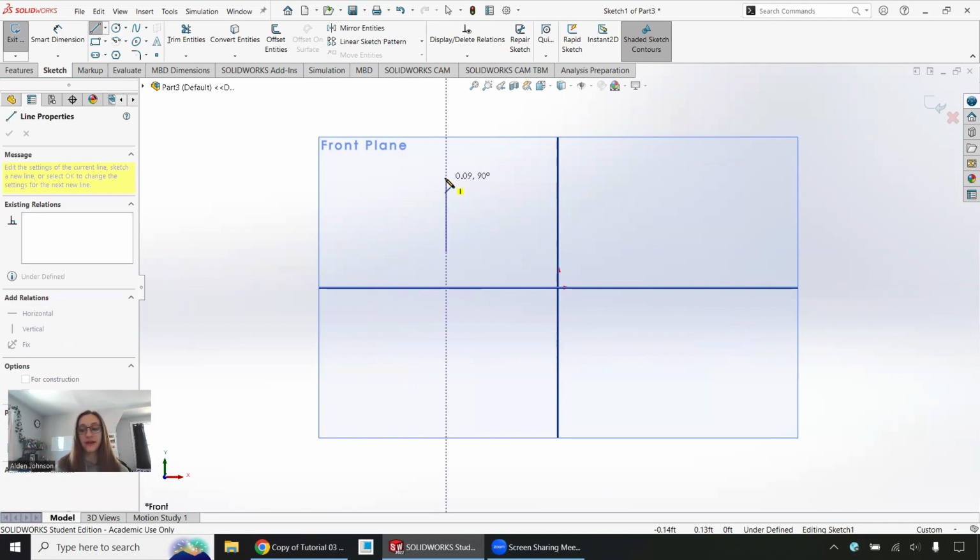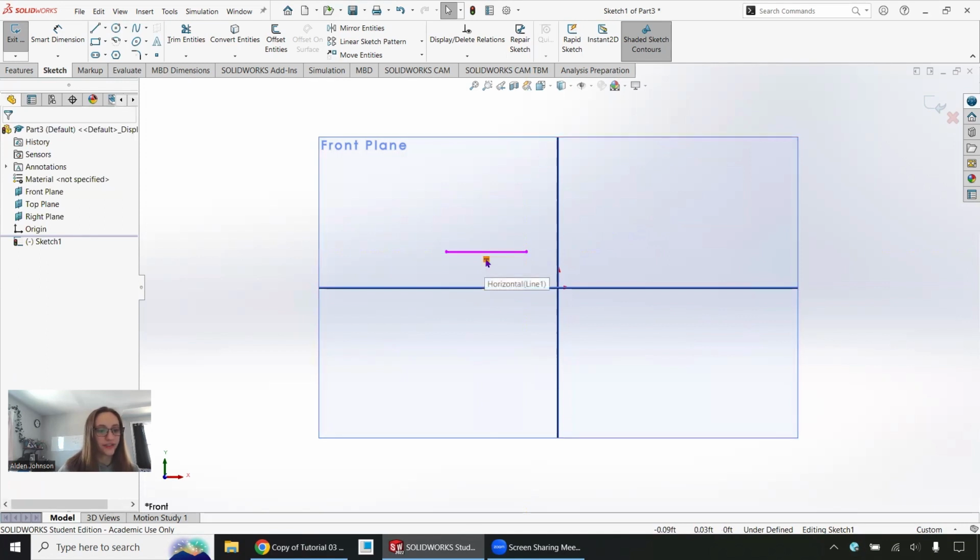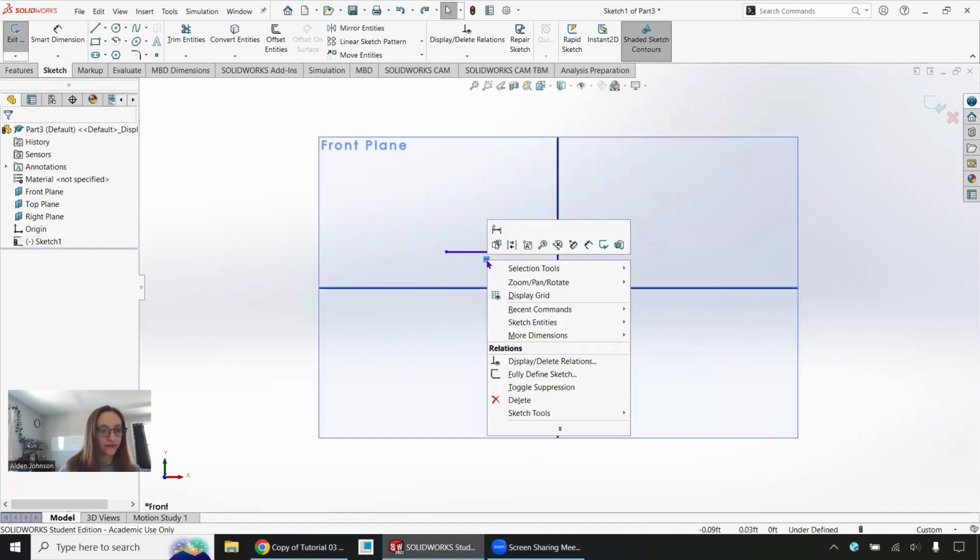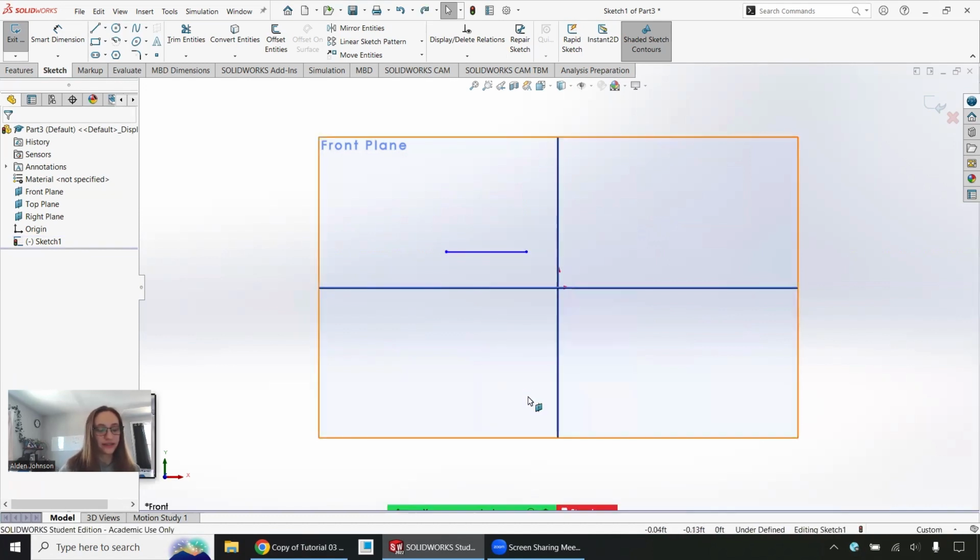These are examples of geometric constraints. If I opt into these, SOLIDWORKS will keep this line horizontal, no matter how else I modify the part, and prevent me from changing it, unless I go in and remove that constraint by clicking on it and hitting my delete button. I can also delete it by right-clicking and hitting delete.